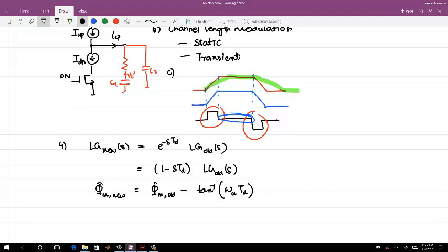So you have to take this into account. If the reference frequency goes high, then what is the total delay in the loop to get a desired phase margin? No, no, omega u will change. I'm saying if I still want the same omega u.